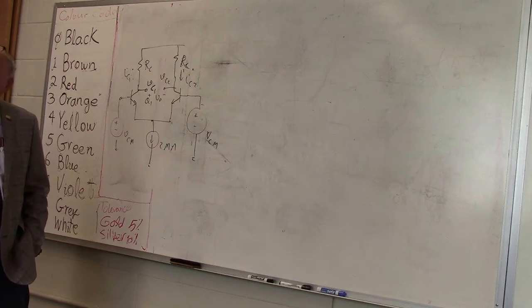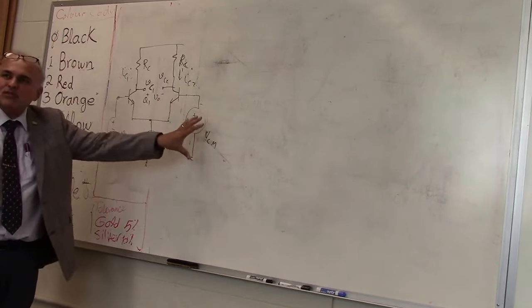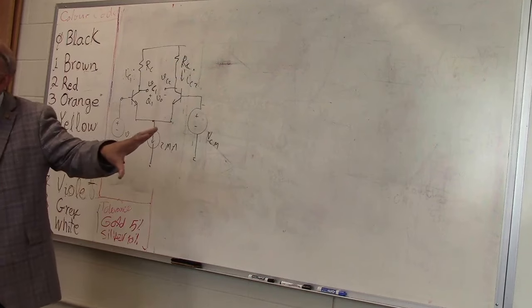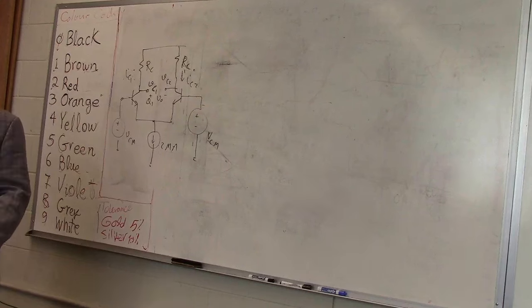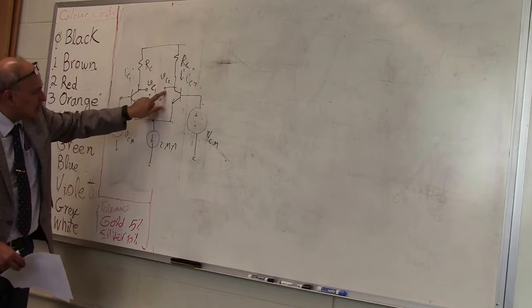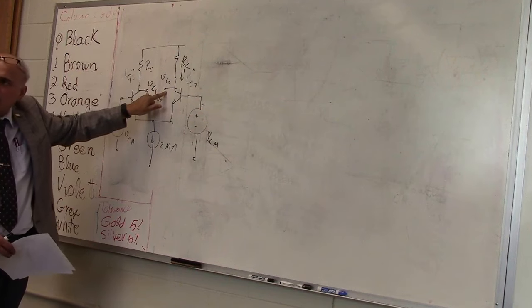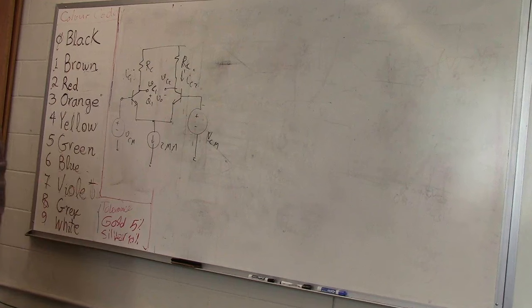No. All right. Now, by the way, in this case, your intuition is correct, because if you expose both sides of the op-amp to exactly the same excitation, which is VCM and VCM, we expect identical responses in both. If there are identical currents flowing in both, this voltage and this voltage are of course identical, and therefore the difference between them is 0, and you would expect no change.